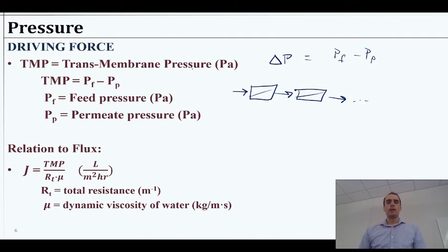So you'll have a microfiltration membrane with a very small pressure drop, maybe then an ultrafiltration with a moderate, small pressure drop, then getting into your membranes that really require a whole lot of pressure. What the membranes are really handling is the pressure difference between the feed and the permeate, because there's still going to be a lot of pressure in the pipe, in the permeate, and the membrane just needs to be able to withstand that difference.